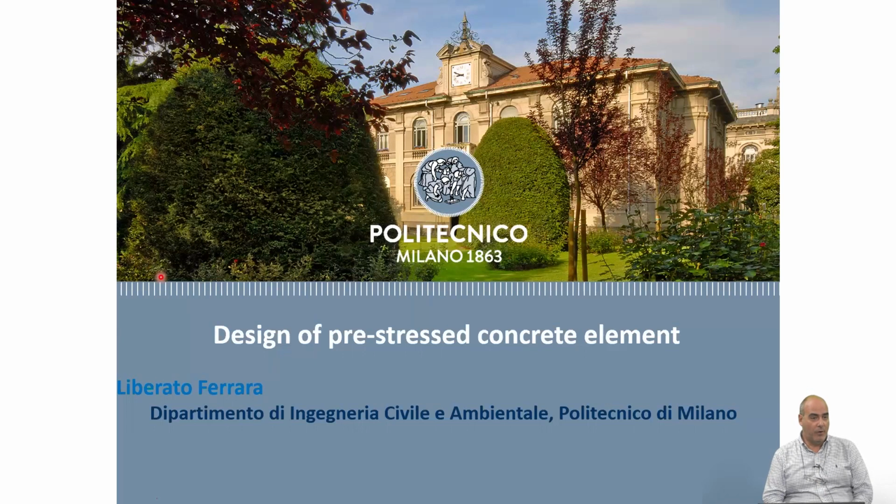And both for conferring to a concrete element some tensile load-bearing capacity. I say load-bearing capacity, not strength, because concrete has a tensile strength. The tensile strength is very limited. But what we want to do is not to give tensile strength to concrete, it is to give to a concrete element some capacity to bear tensile stresses. And for this, and also to temper the brittleness, we use steel. We use, well, let's say we use reinforcement.